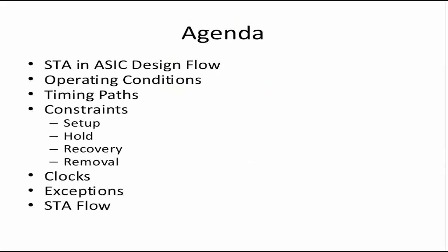The agenda is this: we will look at where STA fits in the ASIC design flow. We look at the importance of STA. We'll look into the operating conditions in some detail. Then we'll go on to the timing paths and constraints. We'll have a relook at the different sorts of constraints that STA checks.